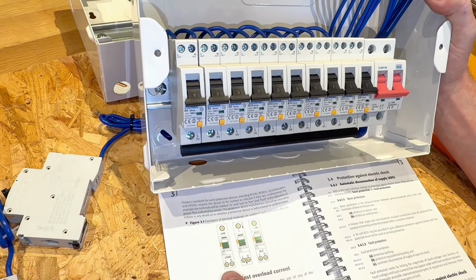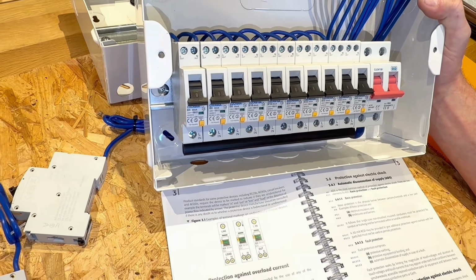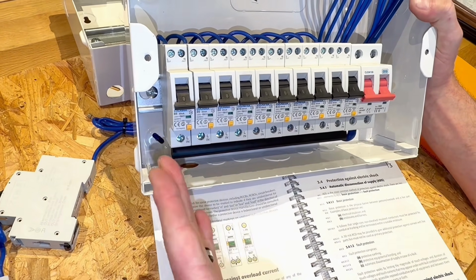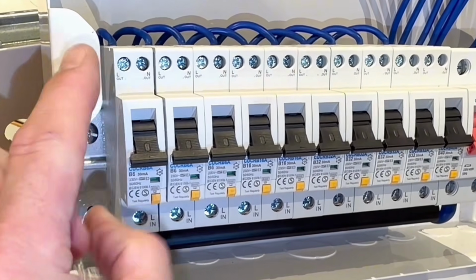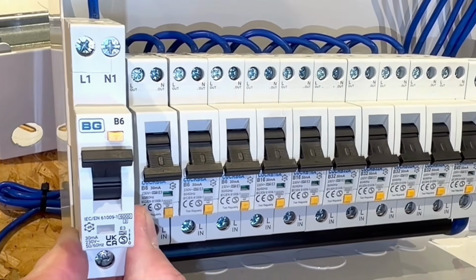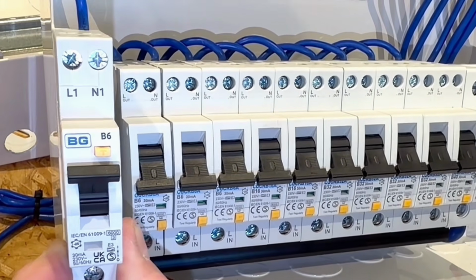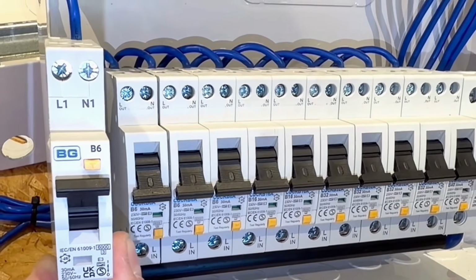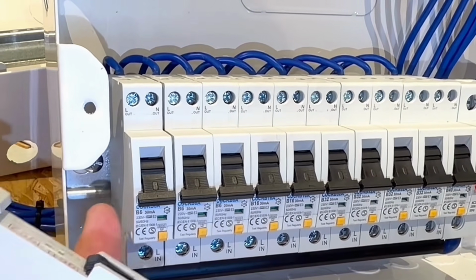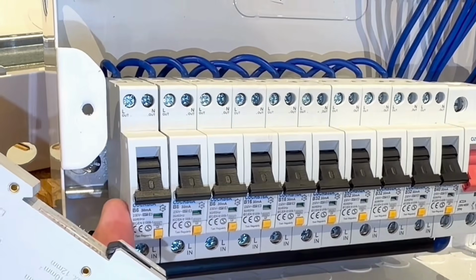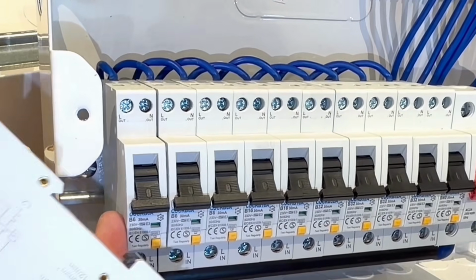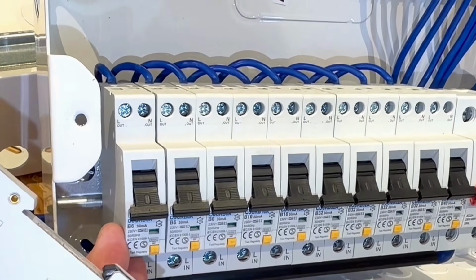So possibly with some help from BS 7671, which I don't think is as much help as it can be, we could look at this older consumer unit. When you say older, it's just been improved slightly from the point of view that we can see that these are unidirectional. This RCBO on the end needs replacing. It would need replacing if you had an inverter for, say, micro wind or solar PV, with one with no labels defining its direction, making it bi-directional, removing the unidirectional device that's already there. This is something you want to keep an eye out for, things like EICRs as well when you're going in there, just to confirm whether the device is correct for the actual circuit it is. And we saw in those older ones that by default, it actually does mean it complies.